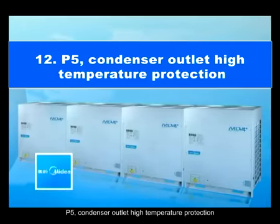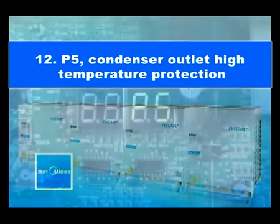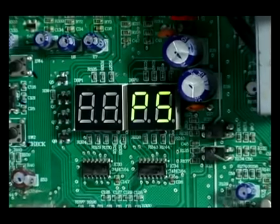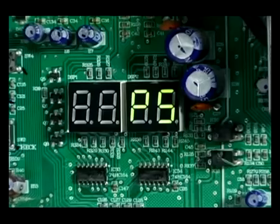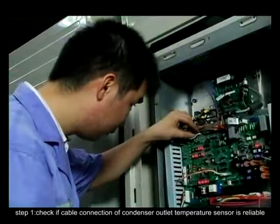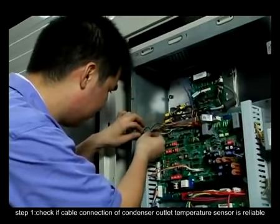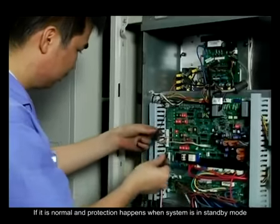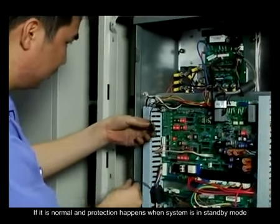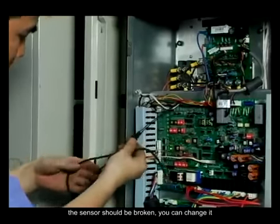P5. Condenser outlet high temperature protection. Repair instructions when P5 appears. Step 1. Check if cable connection of condenser outlet temperature sensor is reliable. If it is normal and protection happens when system is in standby mode, the sensors should be broken. You can change it.